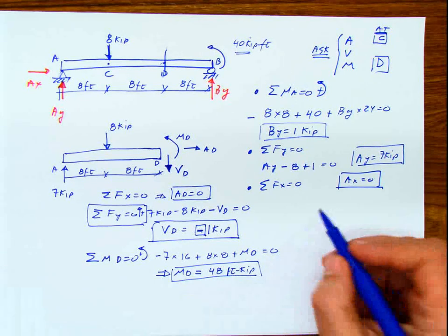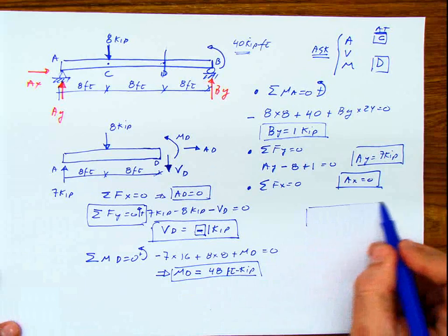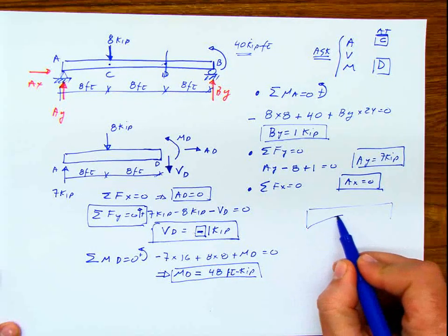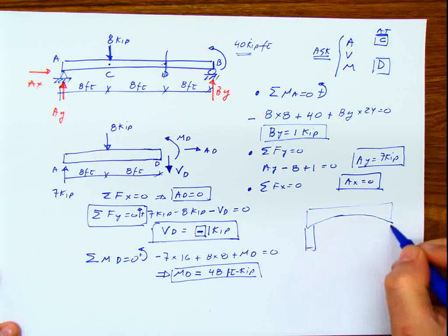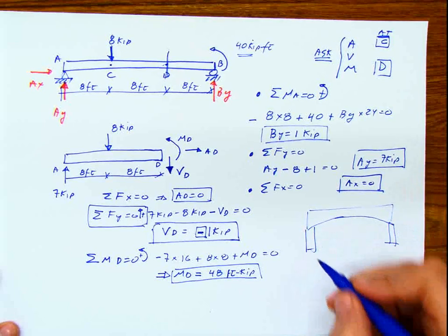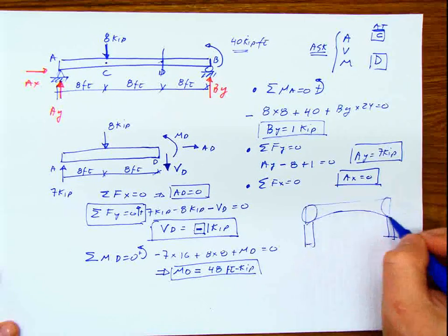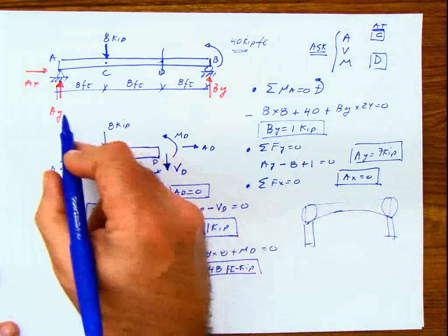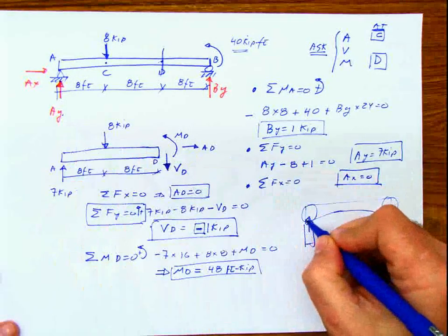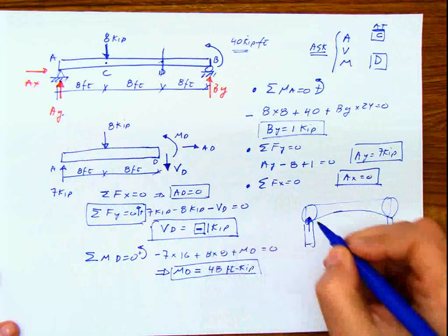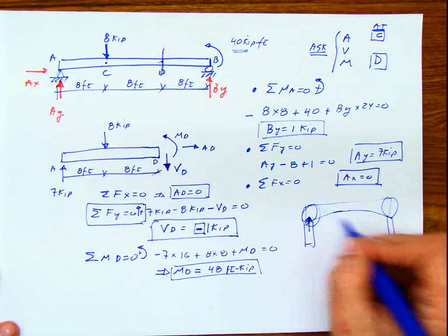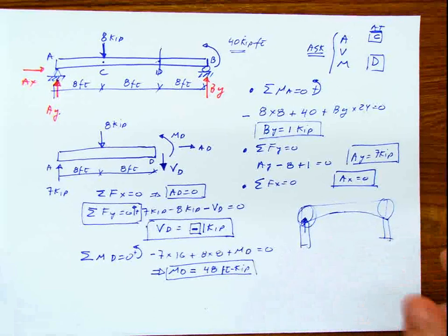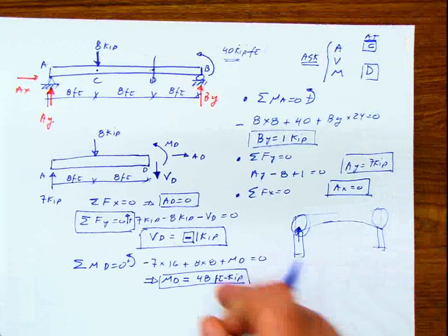That's why, when you have a steel bridge like that and these are the supports, this part is bigger, because at the supports the reaction is going to produce a bigger shear than at the center. That's why this part should be thicker than that, and also for the moment at that point. Okay, that's the first part of the problem.